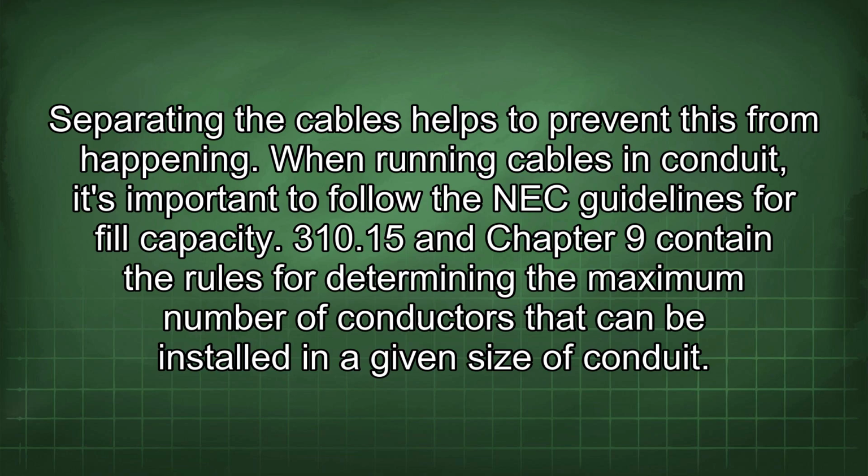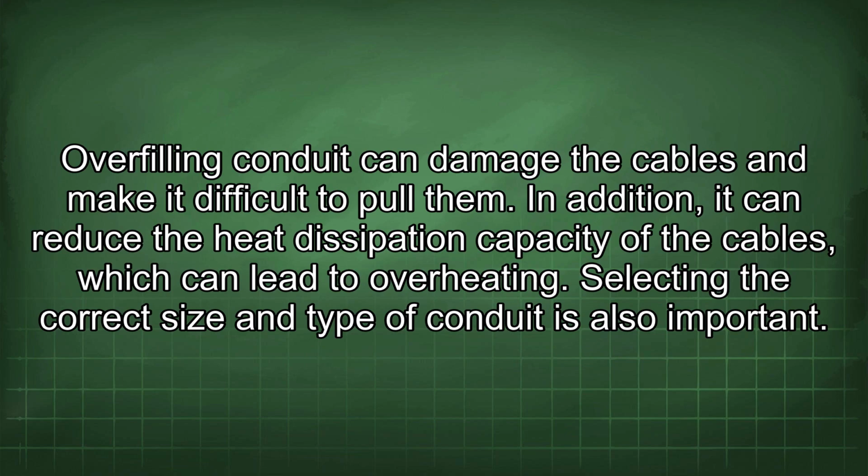Section 310.15 and Chapter 9 contain the rules for determining the maximum number of conductors that can be installed in a given size of conduit. Overfilling conduit can damage the cables and make it difficult to pull them. In addition, it can reduce the heat dissipation capacity of the cables, which can lead to overheating.